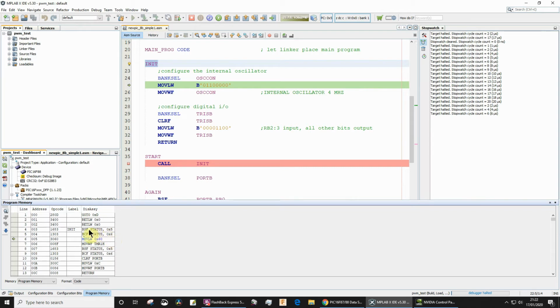So those are setting the RP0 bit, and then clearing the RP1 bit. So yeah, sure enough, these two instructions actually took that's why it took 2 more instruction cycles. So we're currently at a move a literal into the working file register. So that's only going to take 1 instruction cycle.